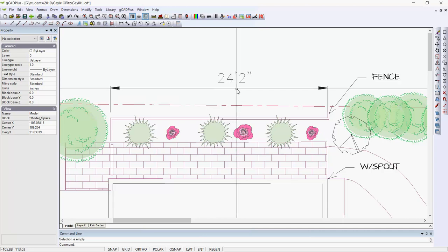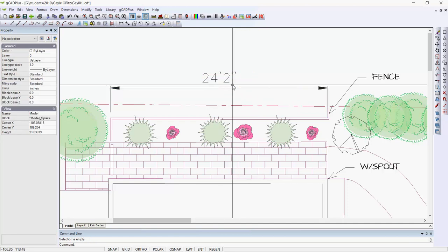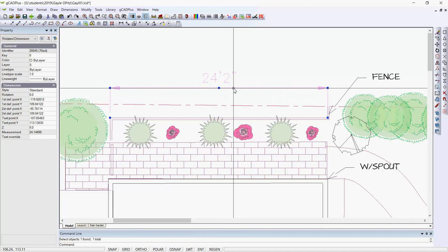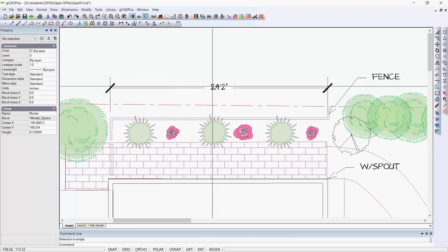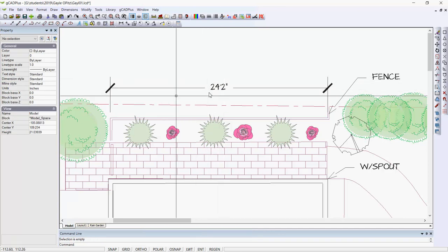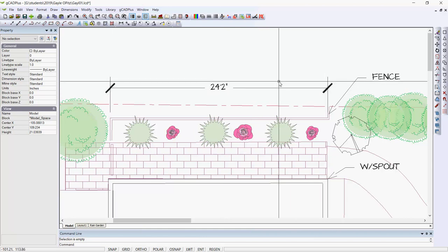Well, as an aside, if you select a dimension and the text is not centrally placed, just slide along like so. But this drawing's got several other dimension styles, and it's a simple matter to change from style standard to, say, style architectural. And now our text is in the line is broken. Can you see that the marker, the arrowhead marker, has changed, and it's a little large?